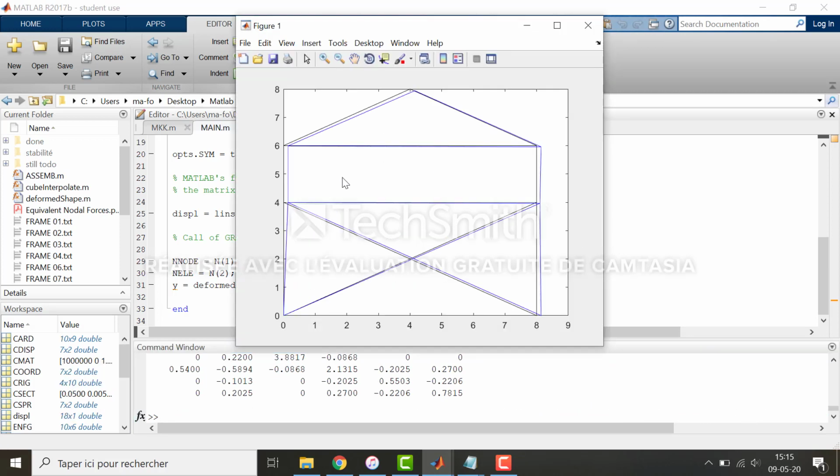And as we see, we have the loading on the left facade. On this node, yeah, this one is a little bit lower than it should be because there is a vertical loading, and we have the temperature variation that we don't see much as well, but it takes it into account in the calculation. We can see that the rightmost fiber of this facade is a little bit shorter, and it flexes a little bit. There is a little deflection.